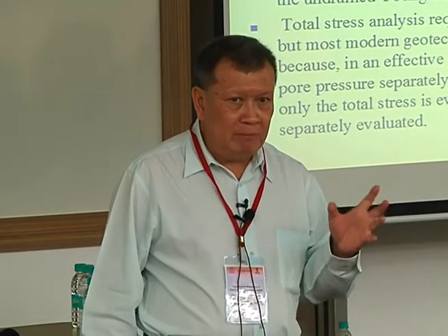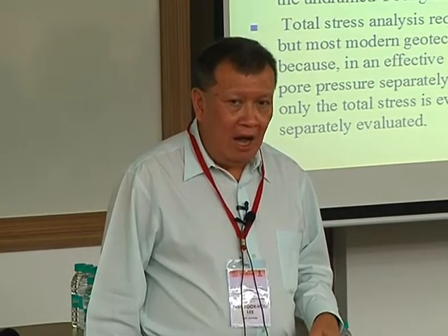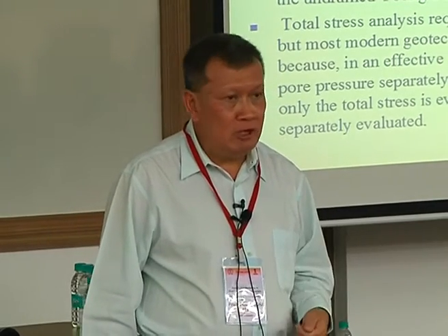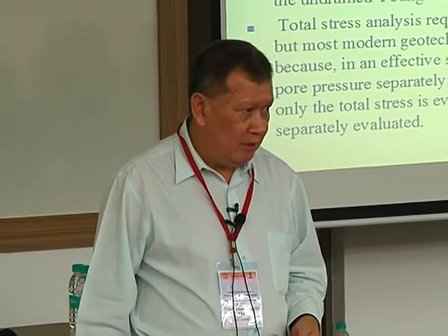And you can see sometimes in some cases, people are interested or concerned about pore water pressure, in which case you have no choice but to use an effective stress program.